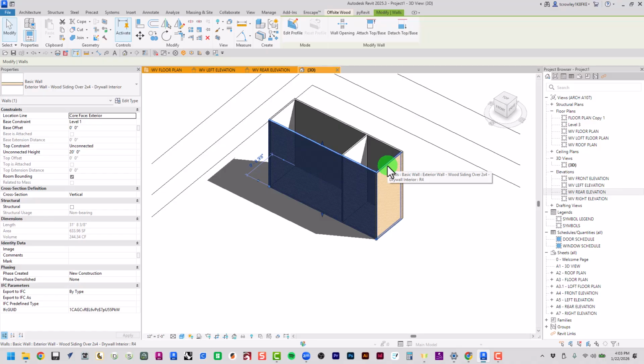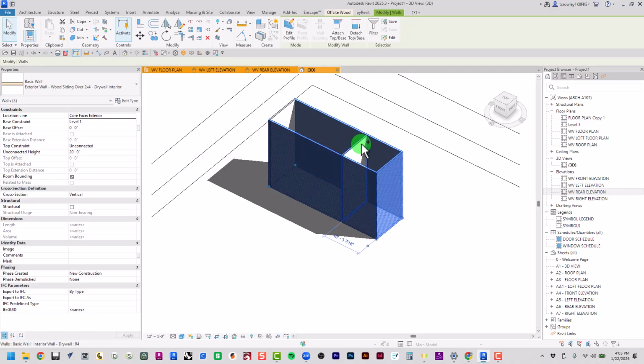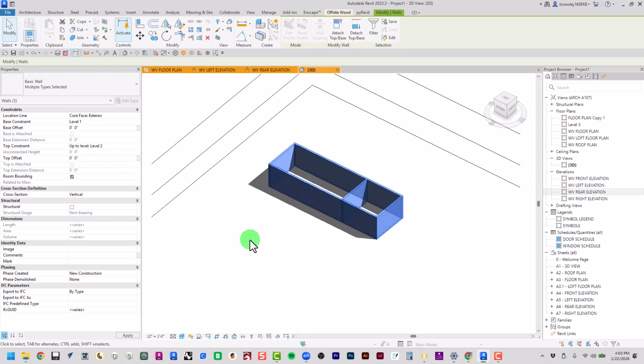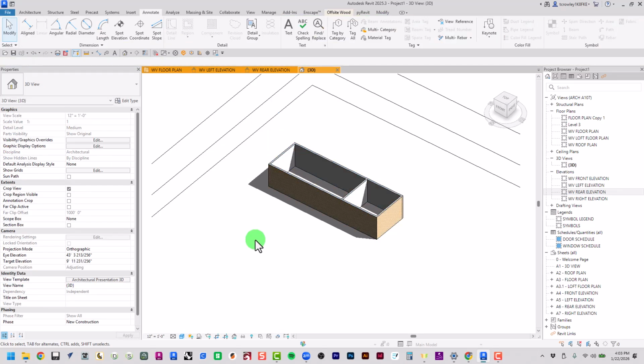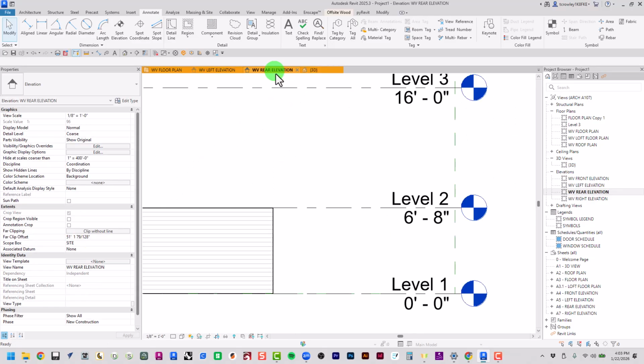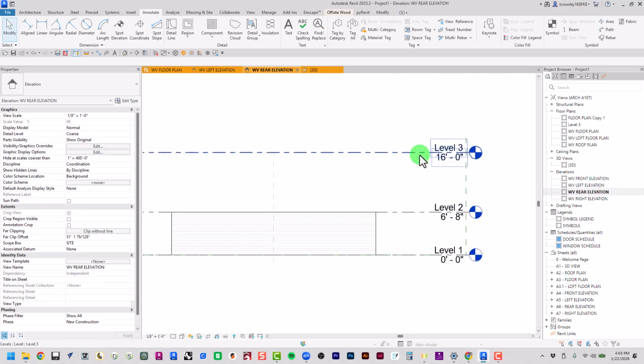So when we're building our tiny house, in relation to the heights, we're talking about top plate heights, right? There is the mud plate, which is the bottom part of the wall frame. There's all the vertical studs that we're all used to seeing and mounting our TVs to. And then in wood construction, there's double top plates, right? So there's one plate on the very top and then one more right above that. So understanding what the relationship between the mud plate and the double top plate is tells us that floor height,